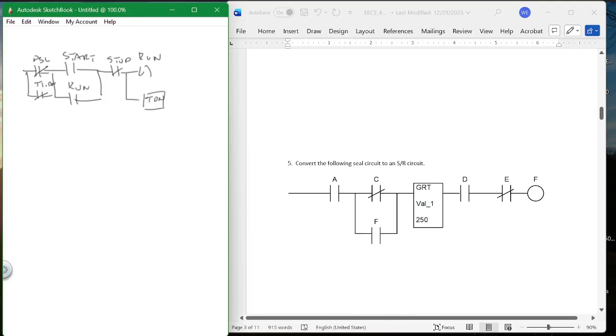Now here is one where you're being asked to find the start and the stop part of the circuit, and I'm mixing it all up, and I'm also putting in something that's not a contact, but this is a contact. It's a go no go piece of the circuit, and basically how do you do the negative of a greater than? Less than or equal. So what's the opposite of a greater than? Less than or equal, LEQ.